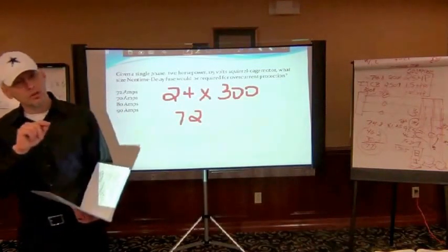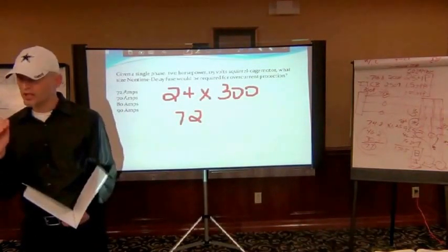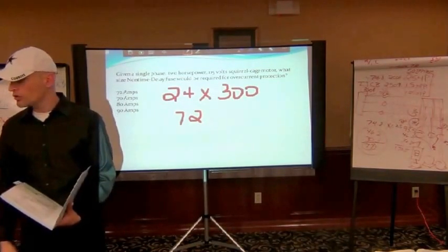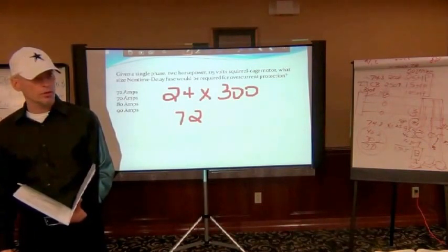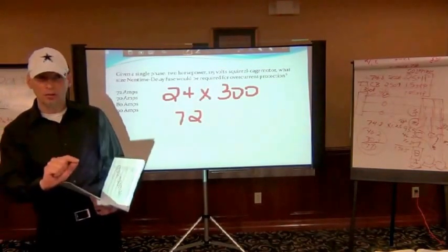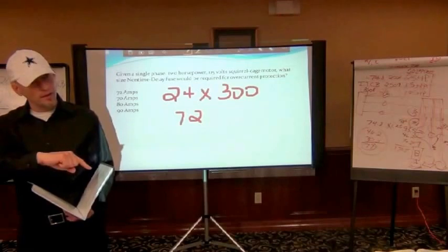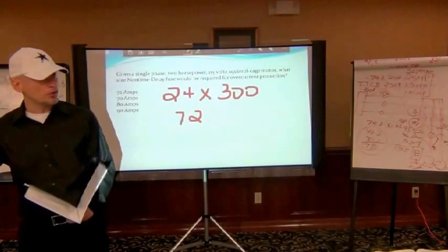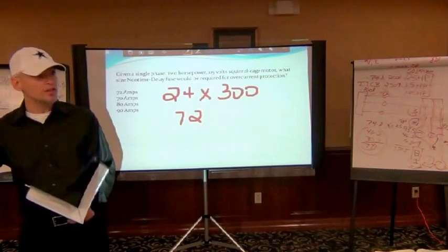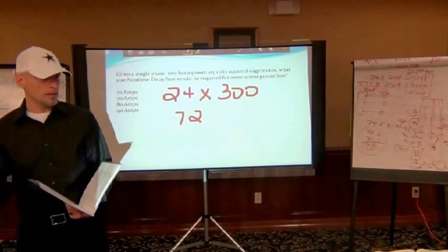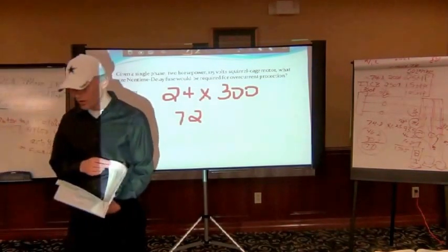If you were paying attention to a service factor of 1.10 and an ambient temperature rise of 50 degrees, what value would you use to size a heater for that same motor? 115%, right? So if you're sizing wire at 125%, and you're on the heater table where they're trying to put you, you're using 115% to size wire. You see what I'm saying? Wrong answer. It'd be there for you to pick, but it wouldn't be the one you want to use, right? But what was the question?